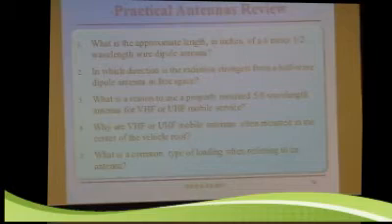112 inches, that's right. Now remember, you can calculate it out. You don't have to remember it: 468 divided by frequency in megahertz will crunch it right out for you. So if you happen to forget it, just remember 468 divided by frequency in megahertz. Is that 112 inches? Is that the same as those big long antennas that used to be on police cars?